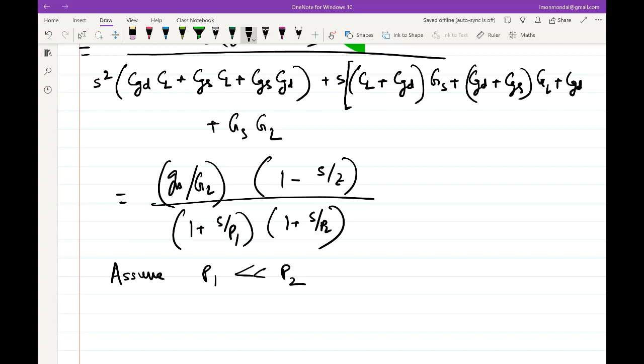Okay. So if that is the case, what is P1? Tell me. So let's say AS squared plus BS plus C equal to 0 is my quadratic. It has two roots, which are poles P1 and P2. Let's assume a mod of P1 is much less than mod of P2. That is, I mean, they are separated apart. By the way, I will remove the mod after some time because that's how circuit designers talk.